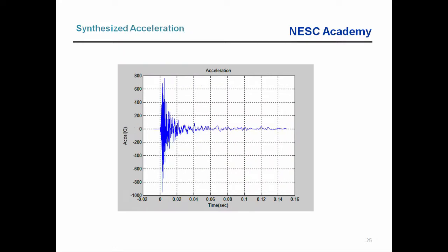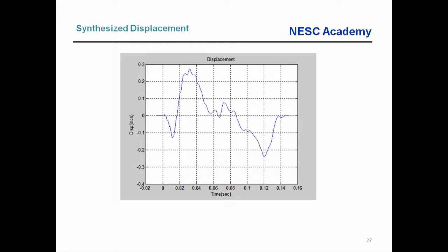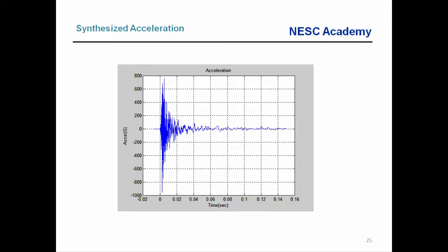So now we have a consistent set: acceleration, velocity and displacement, and this indicates that the acceleration time history would be suitable to base drive a structural dynamics model as part of a finite element analysis.